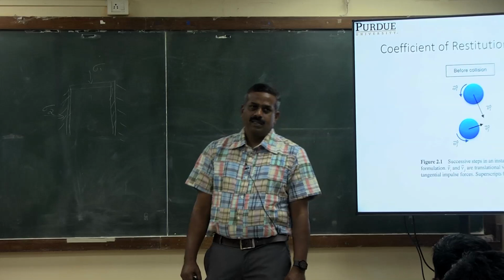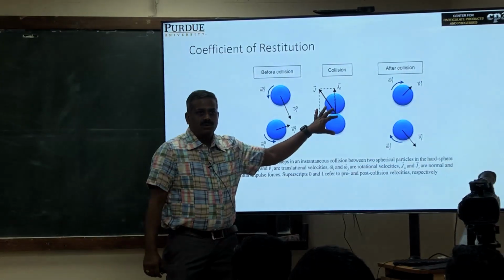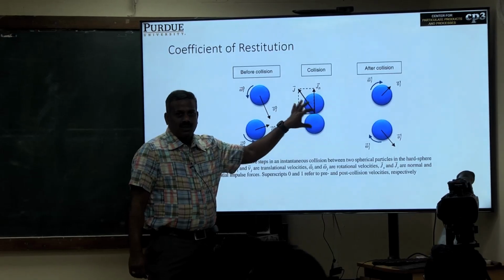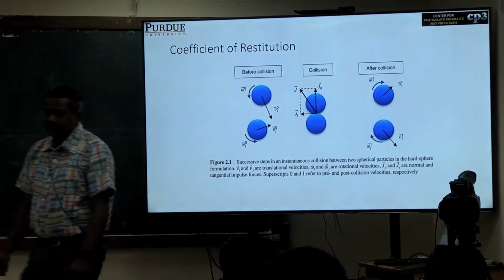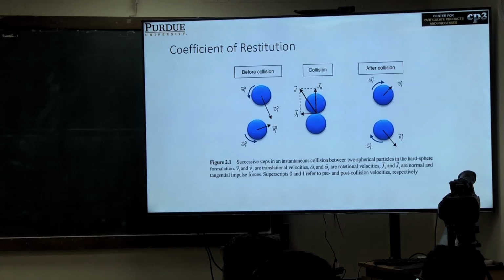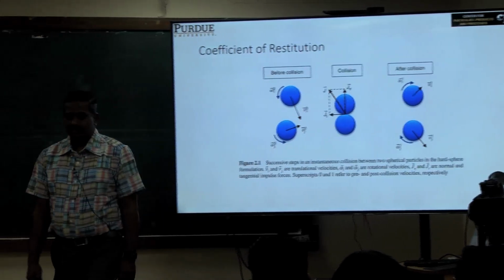Elasticity. Okay, so if it's plastic, what happens? During collision, it loses some material, right? So other than energy, we are losing some material. So we assume that it's elastic, and it's normal contact between those. Contact, we assume normal contact. Measurement in general is based on the velocity before and after impact.